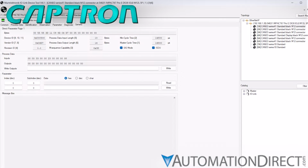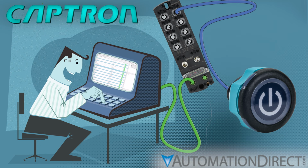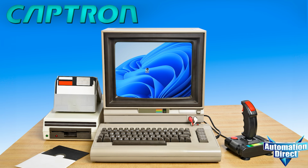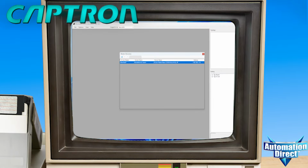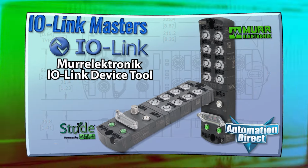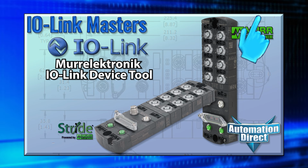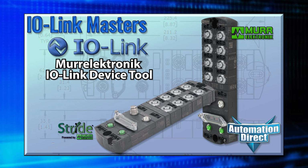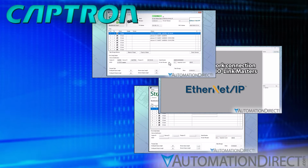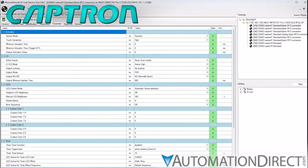To look at the configuration options available through IO-Link, we'll need to have a Caneo series switch connected to an IO-Link master and have our PC or laptop also connected to the IO-Link master via Ethernet IP. We'll furthermore need to have the IO-Link Master's Device Tool application open and provisioned with the proper IODD file for the switch we'll be examining. If you need to brush up on any of that, please refer to our IO-Link Master's Device Tool video by clicking here. That video demonstrates connecting the IO-Link Master's Device Tool to a Caneo series push button and covers basic operations. But here we're going to go deeper into the configuration possibilities.